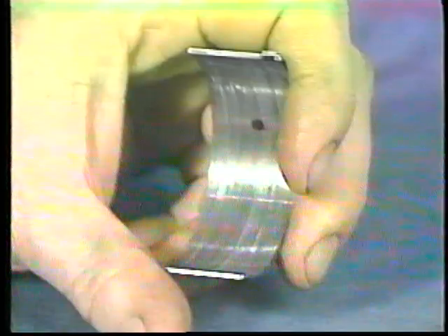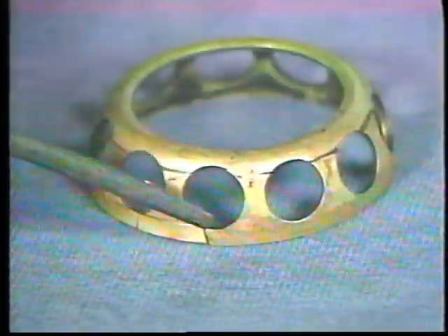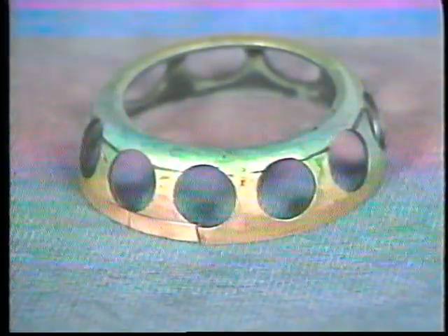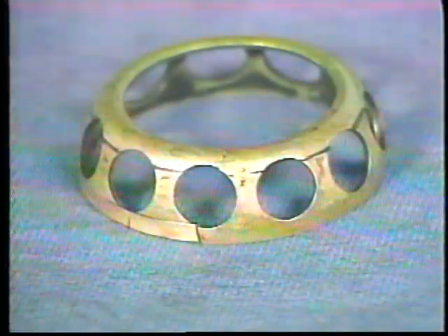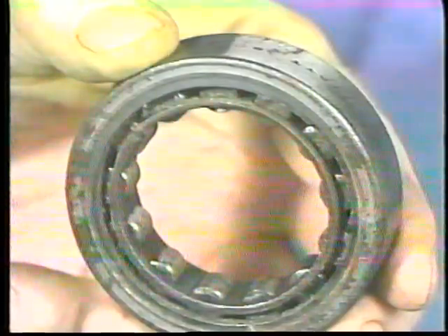With a constantly changing load direction, these noises will be naturally loud and easy to detect. The sound can also indicate excessive end play or end float in the shaft. A high tone or whine often means the bearing has been Brinelled. That is, the rolling elements have permanently dented the races. Random or intermittent clicks probably indicate a problem with the cage or retainer, damaged rolling elements, or dirt in the races. A crunching, grinding, or growling sound can also indicate dirt. Or it may indicate seriously worn rolling elements or races.